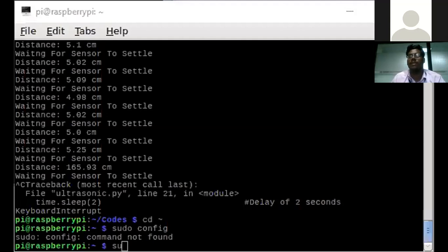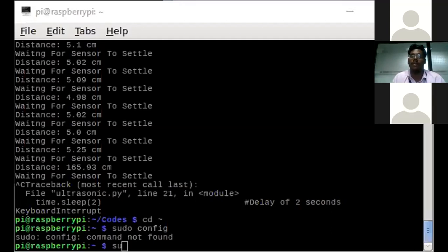So this is the GPIO 40 pin. The pin number differs from the GPIO pin. Whenever you mention pins in Raspberry Pi, those are GPIO pins, not the pin numbers. So GPIO is the pins you mention in your code. Please be careful while writing code. You give the GPIO pin, so whichever pin you need, just cross verify and communicate it.